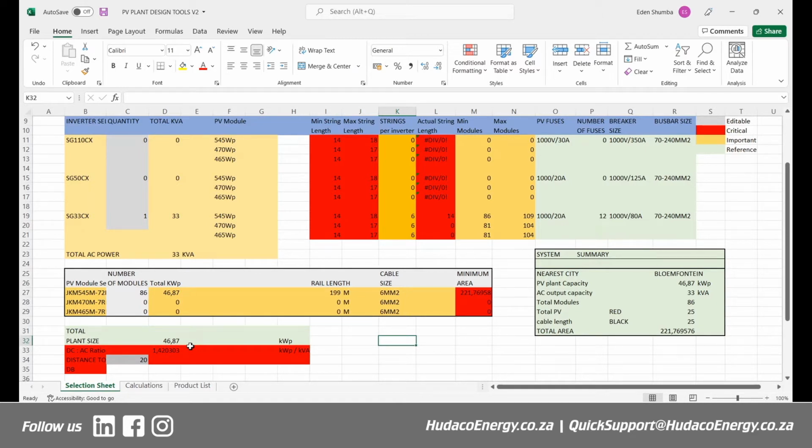So I would recommend that if you're using a 33CX, go for smaller panels, because it gives you room to be within the acceptable ranges very easily. As you have seen here, if we just use even the minimum recommended number, your DC to AC ratio is already too high.